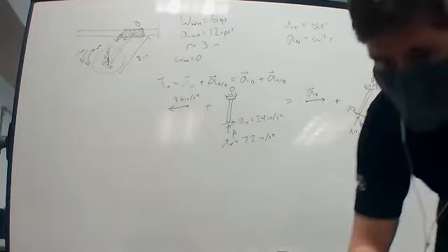From there, it's just like the others where we can say we have knowns, both of these are known, one unknown, and a second unknown. But using some of the forces in X and some of the forces in Y, we'll have 2 equations, 2 unknowns, and we can solve. So we'll start off with some of the forces in the Y, giving us 0 from this portion. This is perfectly horizontal, so AT is not going to contribute. AN is going to be added, so plus 72. That's equal to 0.